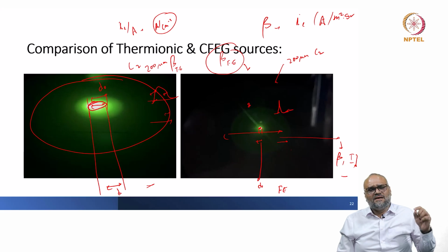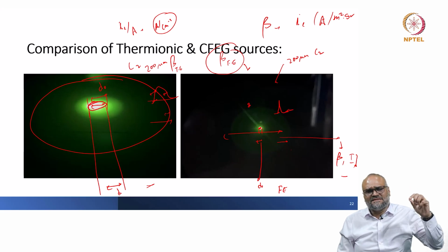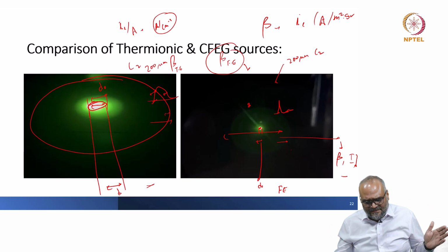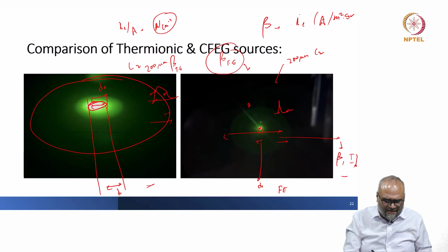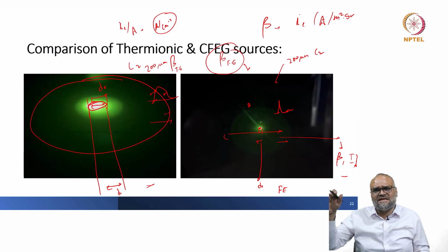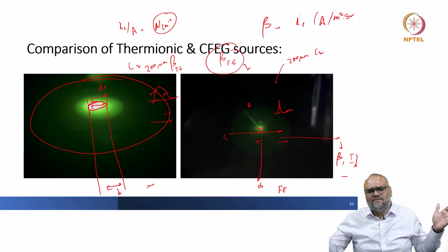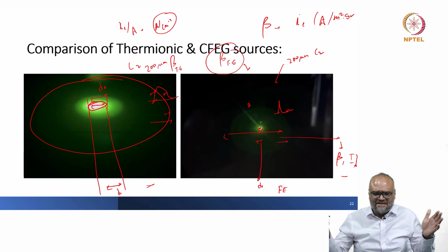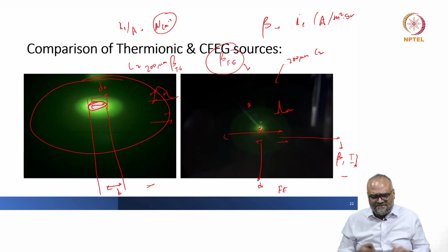It is about how stable the emission current is remaining over a period of time. In a cold field emitter, I was mentioning that the brightness or the current drops over a period of 3 hours or so, whereas a Schottky FEG or a thermionic emitter, once I have a sustained emission, would remain more or less with that particular emission current over a prolonged duration.